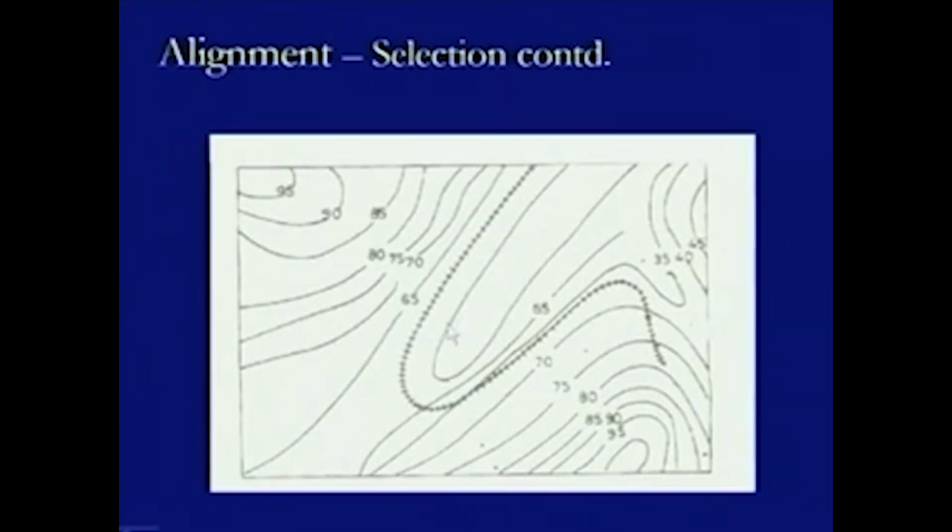So, what we see is that this railway line or this alignment is coming from this direction, in this form, and then we see that the contour is taking a turn. So, it also takes a turn in a similar form, and while doing so, it goes very close to another contour, and this is how it is gaining elevation.